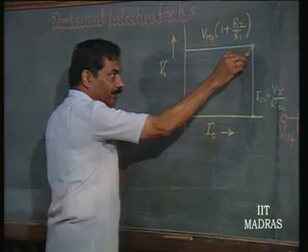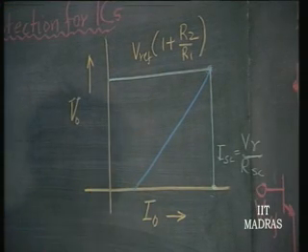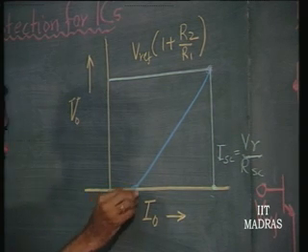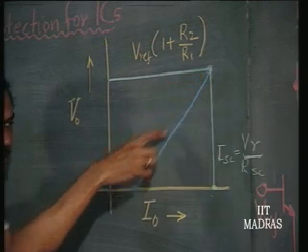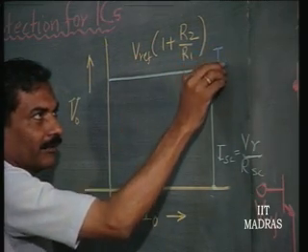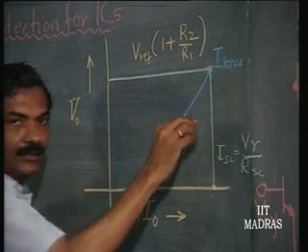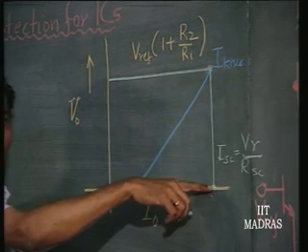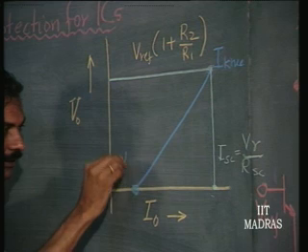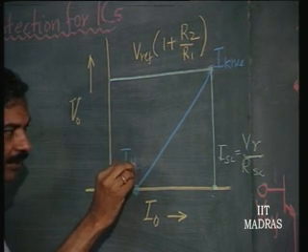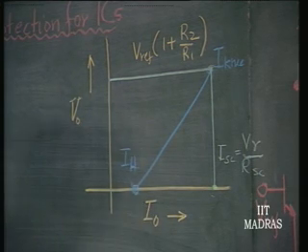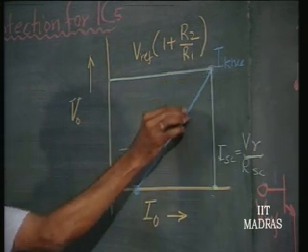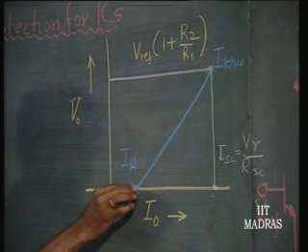So, in such a situation, that particular protection scheme is going to result in what is called a fold back short circuit protection scheme. What it is we will see, but this is what we want. The characteristic of the voltage regulator will have a knee at this point, which we will call I knee, which is the same as the earlier short circuit current, and we will have this as what is called I hold. So, these are the 2 points between which we have to have a line.